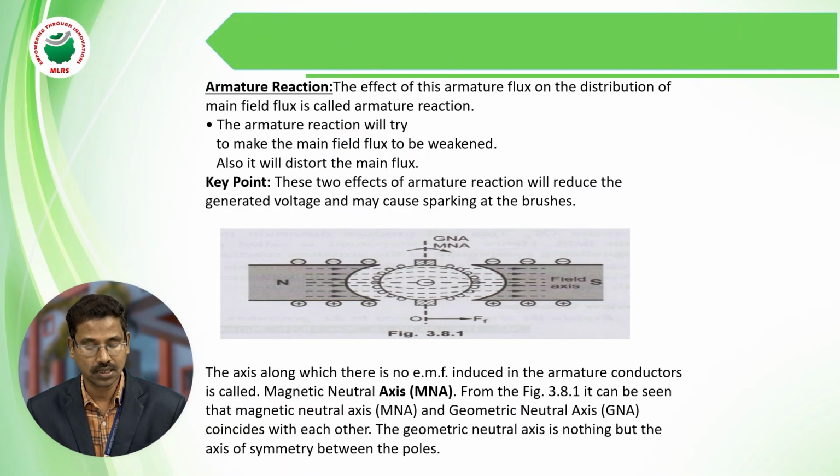So the next one is the armature reaction. What do you mean by armature reaction? The armature reaction is nothing but the effect of the armature flux on the main field flux. Under load condition, we get an armature flux, and this armature flux affects the main field flux.